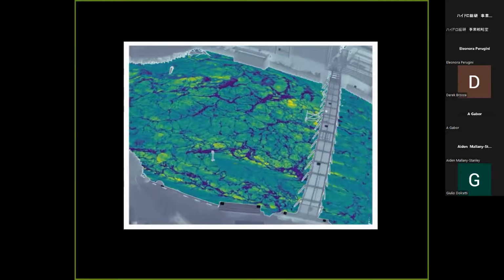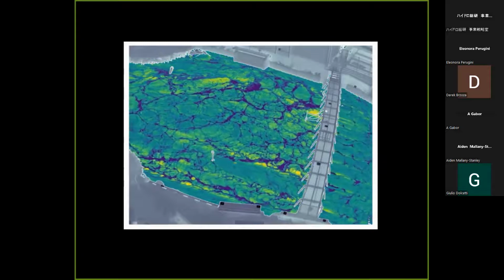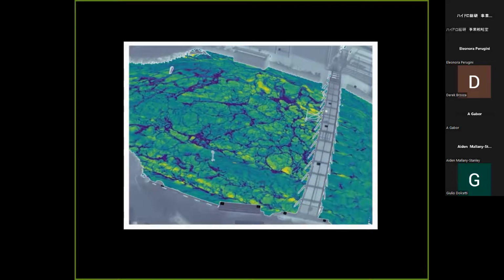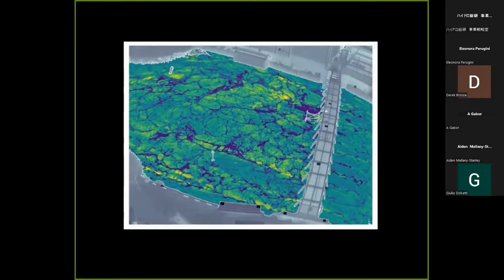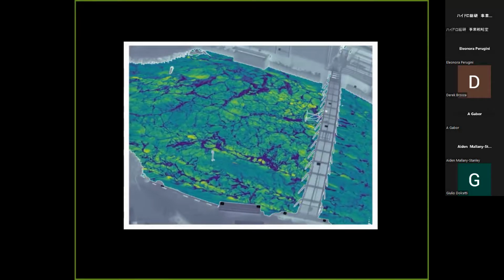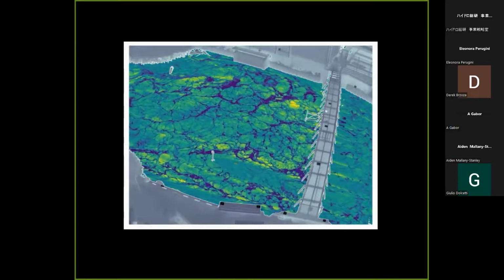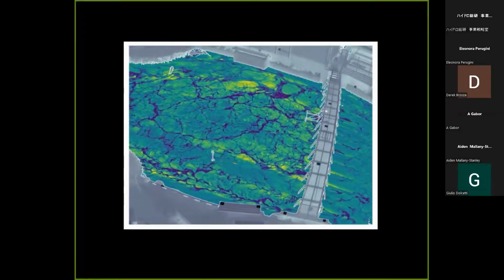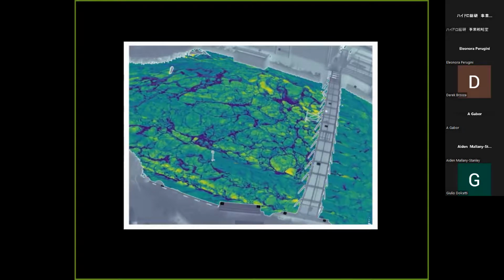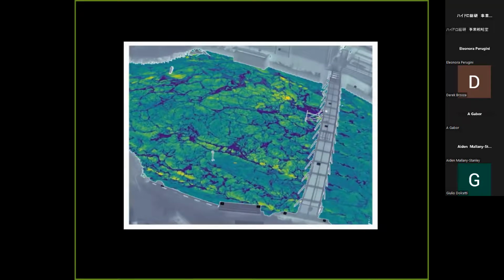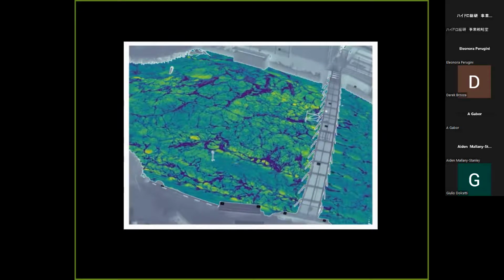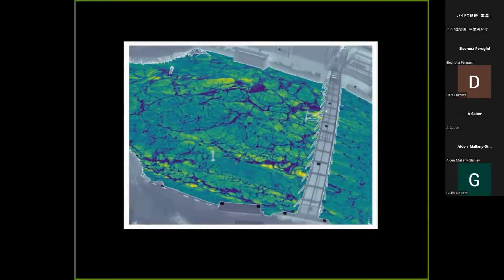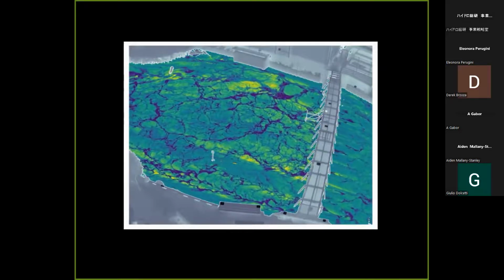Do you get any interference from the atmosphere? That can be like water, hot air, something that can affect the measurements? So on the scale of distances that we're operating at, which is on the order of tens of meters, I wouldn't say that you see the air temperature necessarily affecting anything. Of course, if there's rain in the way or fog, that can be something of an issue. But similar to most optical methods that people have been talking about here, the main issue is once atmospheric conditions start affecting the water surface. So rain might not be that much of an issue as far as being able to see the surface, but if it's disrupting the surface itself, then that could be an issue.